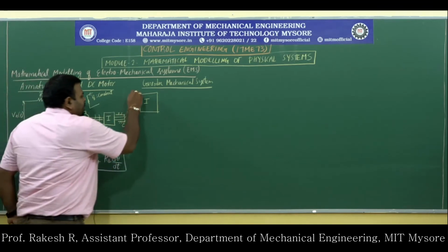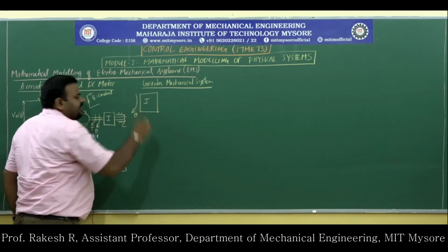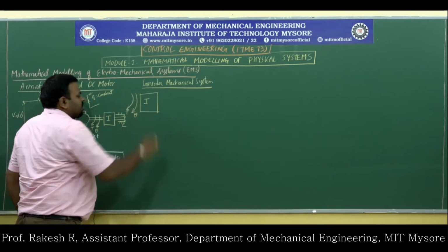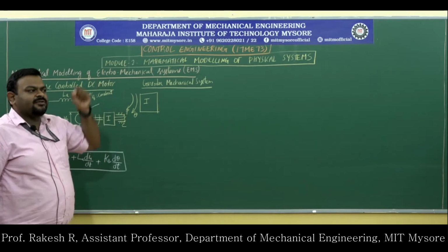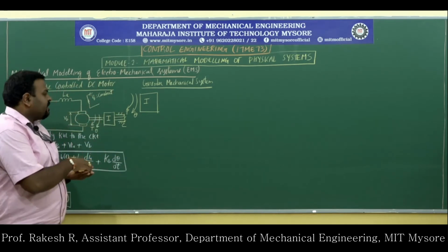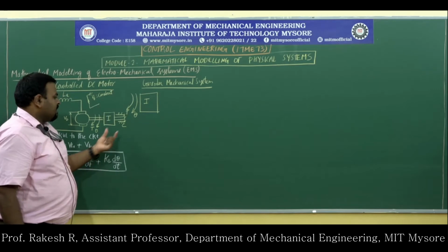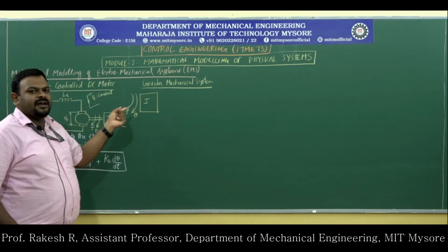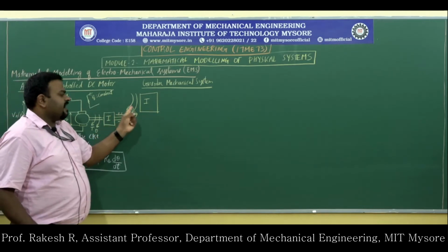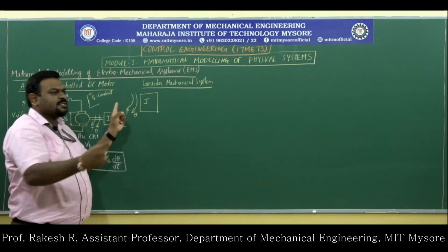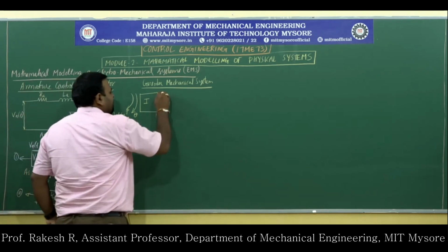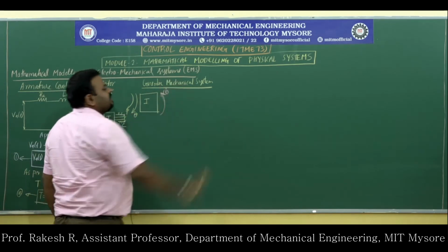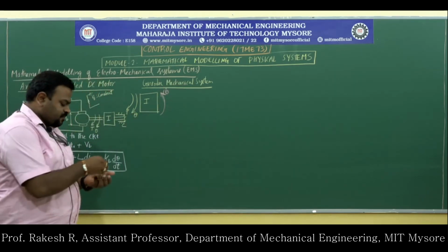I will mark theta, the angular displacement. In the same direction the torque will be acting, so the direction of the external torque and the rotation is the same. To restore this, the damping torque is generated opposite to theta and T. Here T and theta act in the clockwise direction, but C theta dot acts in the counterclockwise direction. So C theta dot is the damping torque.